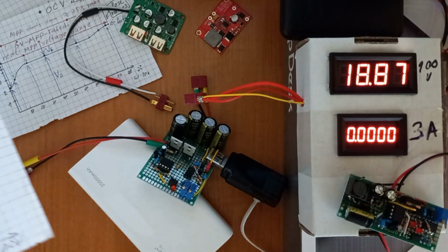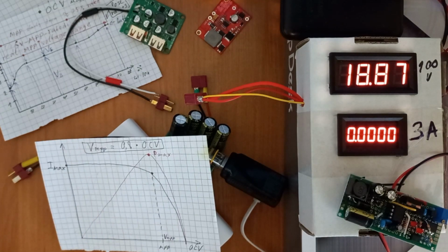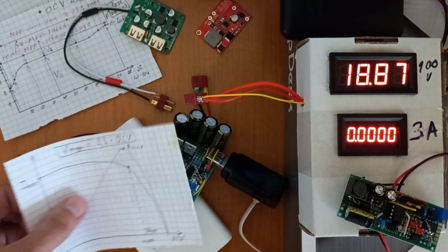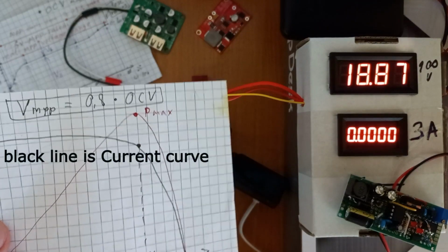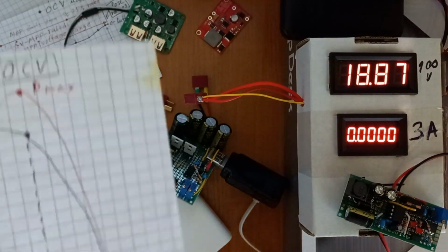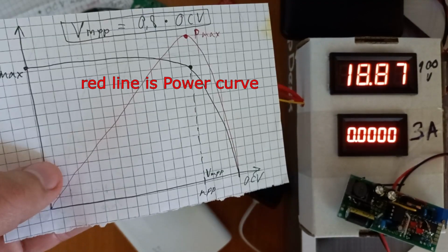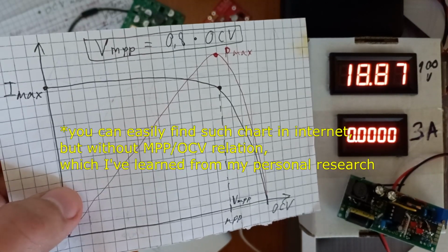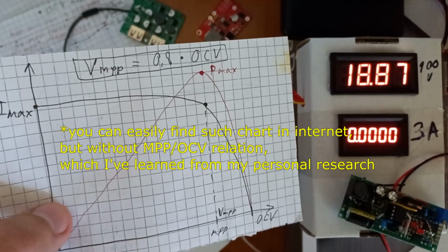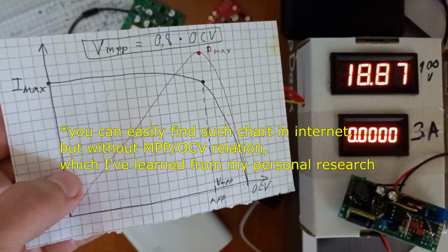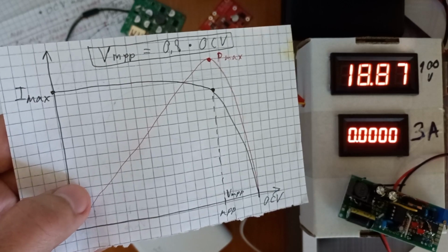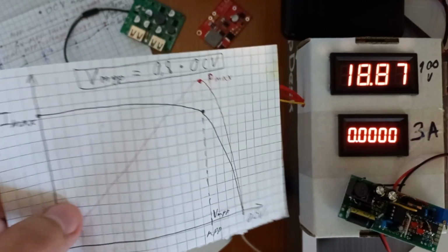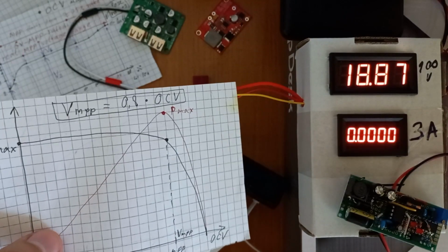First you need to consider is that there are two different efficiency factors for solar controllers: generation efficiency and conversion efficiency. This chart represents solar volt-ampere characteristics. It scales depending on solar panel size and amount of light. We will only consider more or less evenly lit panel, no hard shadows, as this device targets small to medium-sized solar panels, for example, for hiking.